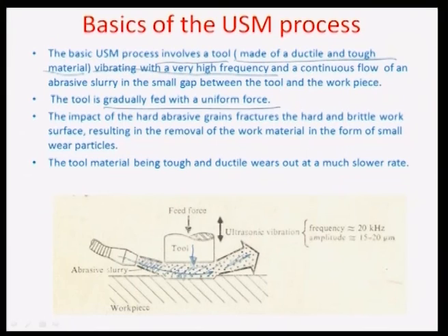One important aspect is that typically frequencies as high as about 20 kilohertz and very small amplitudes at the level of microns are preferred for the feeding tool, and a continuous feed force is given to this tool, which is an important part in determining the MRR, as we will see in the theoretical model that we will create a little later.